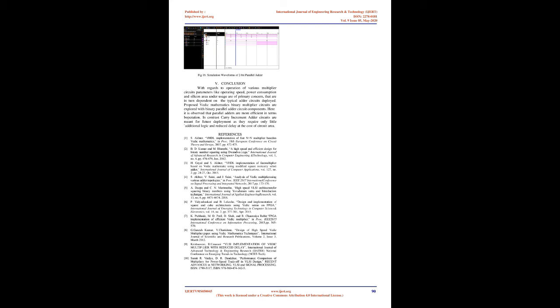For experimental analysis, structural modules of the proposed multiplier are designed using the Verilog HDL programming language. The structural design modules are validated using the Xilinx ISE tool. Experimental evaluations pertaining to the simulated waveforms and results obtained for various other blocks are critically evaluated below. Fig 13, simulation waveforms of 4-bit multiplier. Experimental analysis was performed for 2-bit, 4-bit, 8-bit, and 16-bit multiplications. Simulations relevant for 4-bit Vedic multiplication operations corresponding to different 4-bit input values, A and B, are displayed in Figure 13. Similarly, waveforms relevant to 2-bit operations are shown in Figure 14 below.